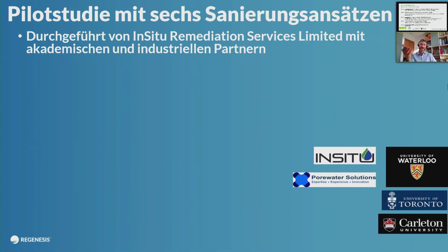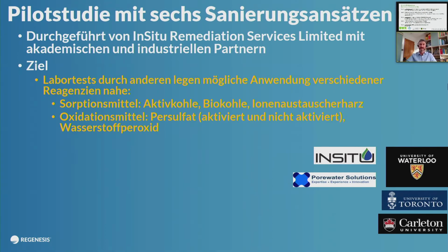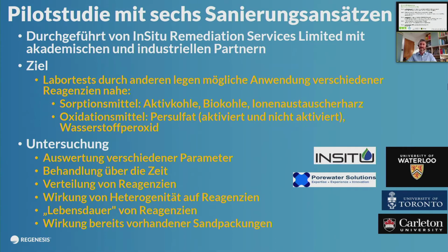And what they wanted to do was look at potential remedial options that have been discussed in literature or tried out in laboratories, such as different sorption materials, such as activated carbon, biochar or charcoal, in ion exchange resin, and then oxidants such as sodium persulfate and hydrogen peroxide. And they want to try that in the field and then test a number of different things, you know, how effective they are, how long they last, how much they're affected by the heterogeneity, what distribution do you get?